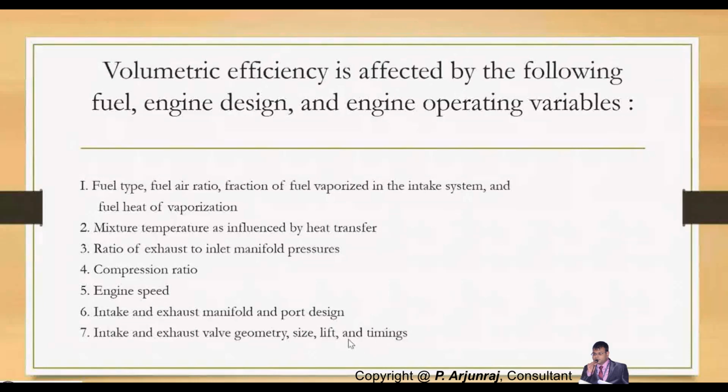And there might be other ways we can look at increasing the volumetric efficiency. The volumetric efficiency is also based on the fuel type you are going to use and the air fuel ratio, because you have lean mixture, rich mixture, and stoichiometric mixture. According to this, your volumetric efficiency will go higher or lower. But again, you need to ensure that you have higher volumetric efficiency. When you have higher volumetric efficiency, obviously your combustion efficiency will be higher, which means your mechanical efficiency will also be higher.